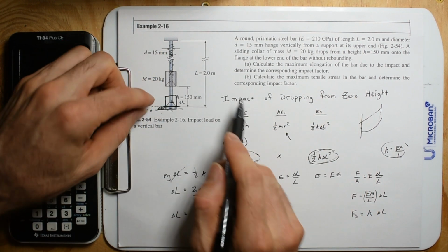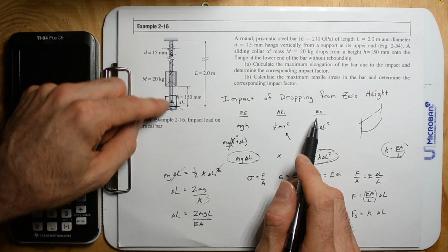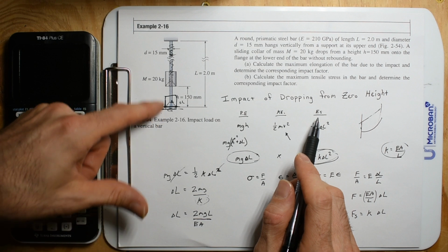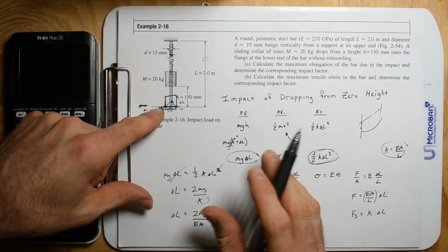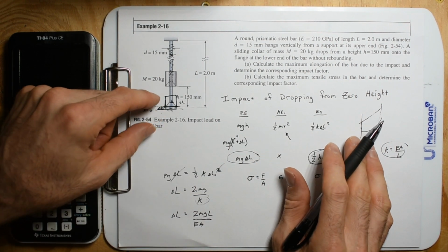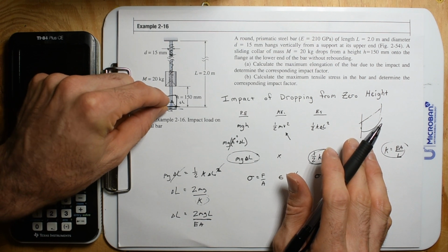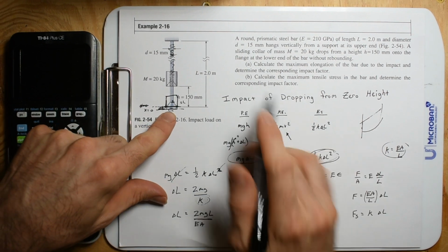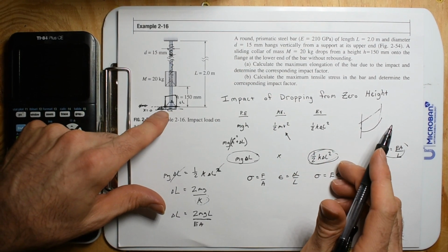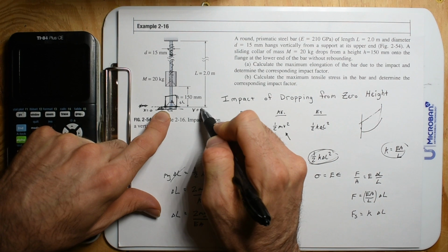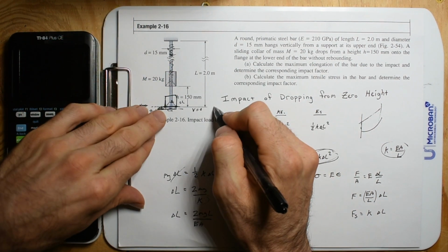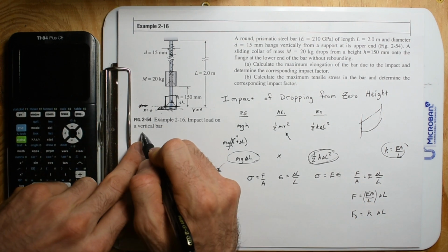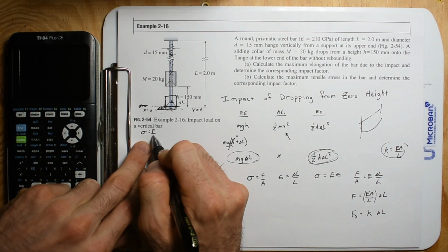And again, if you do shock load it, it's going to vibrate back and forth. It's going to have a max change in length to stop that momentum, and it's going to vibrate back and forth. Obviously, that's imperceptible, and you might not even know it's going to vibrate. But now, if you just took that mass and just very slowly set it onto that spring or rod, then it's going to have a velocity of 0 when you let go. You know what I mean? It's already going to lengthen the spring, and all we have to do is just go back to our material mechanics equations, and we'll write them again because this is just so good.